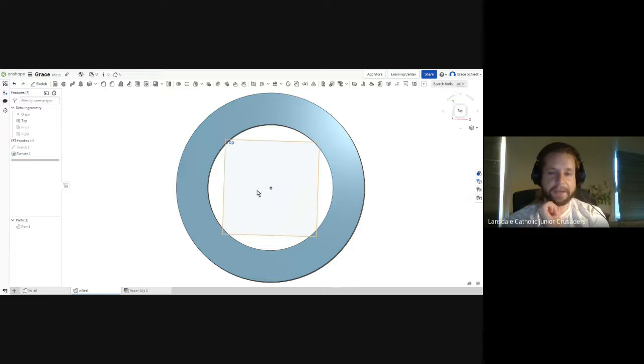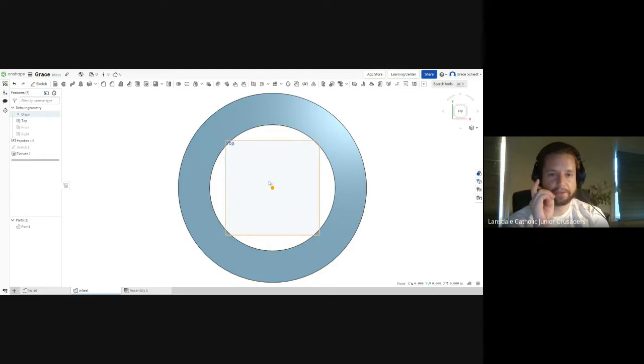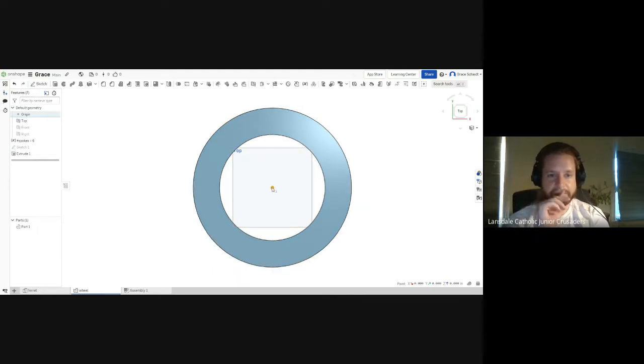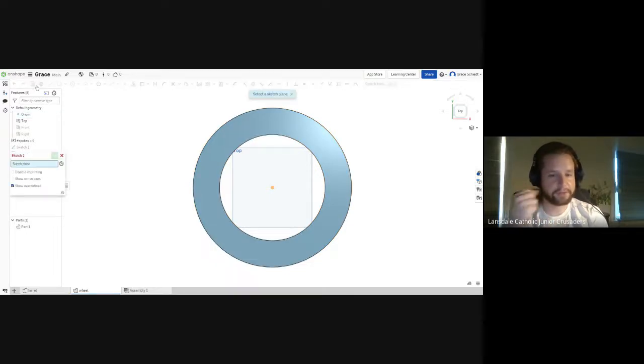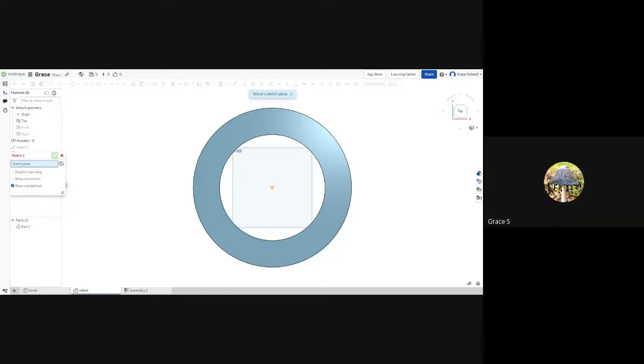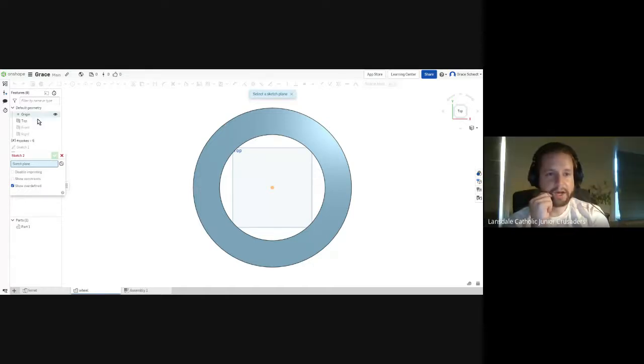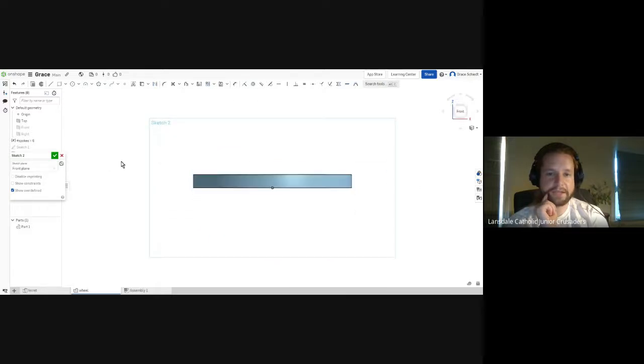And now we're going to make a single spoke. You can make it either the internal or the external ones. It doesn't matter to me. So I would start a new sketch. Do you want the spokes to be round? We're going to do something interesting if you want the spokes to be round. Yeah. All right, cool. You're going to make a new sketch on the right or front plane. It doesn't matter which. Cool. Click N because you're not normal to that plane right now. The N key. There you go.